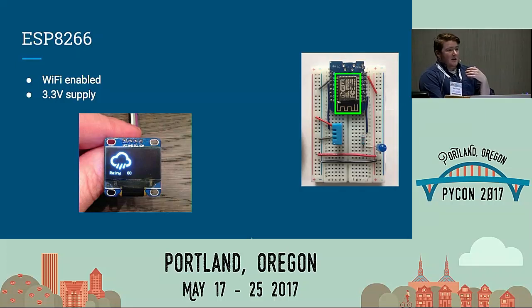It has its own little Wi-Fi access point, so we'll be logging into our little wireless networks to do programming today. It runs on a 3.3 volt supply, so that presents some interesting challenges, in that a lot of Arduino stuff runs on a 5 volt supply, so that's something to be aware of.